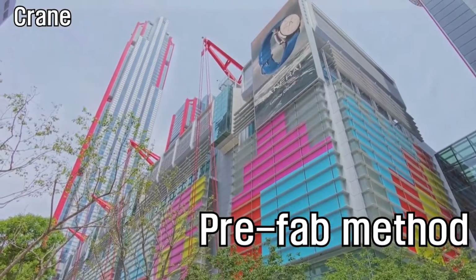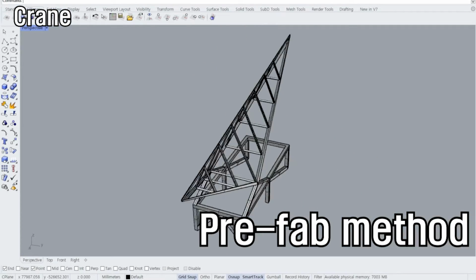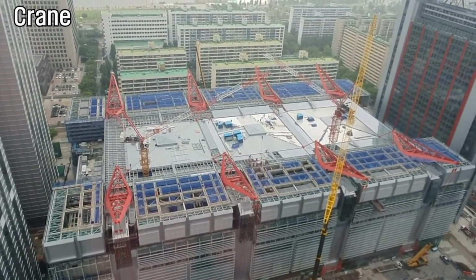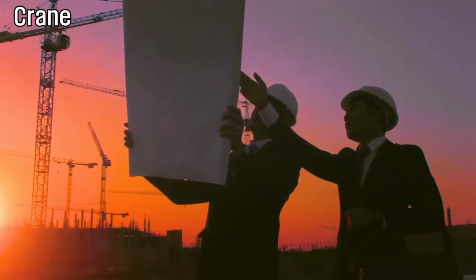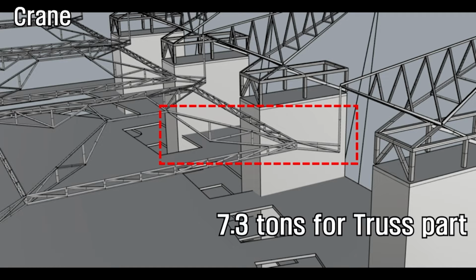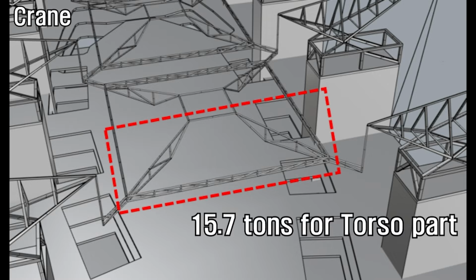The crane was also manufactured in the prefab method like the kite structure, and at the construction field, lifting and installation were performed by each part. There are some issues with the construction of the crane. First of all, the largest truss part for the kite was about 7.3 tons, while the heaviest portion of the torso part of the crane was at least 15.7 tons, which is twice the weight of the truss.